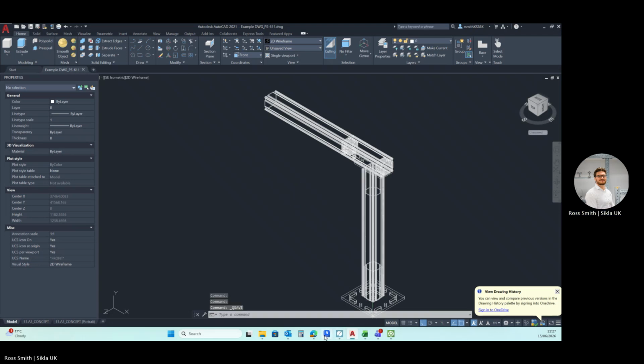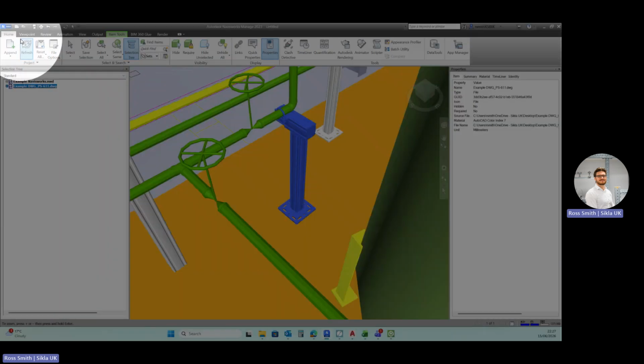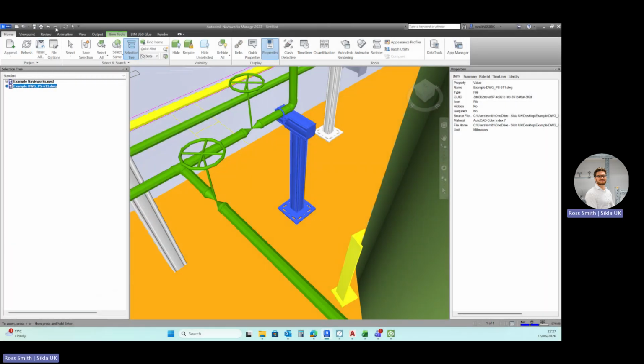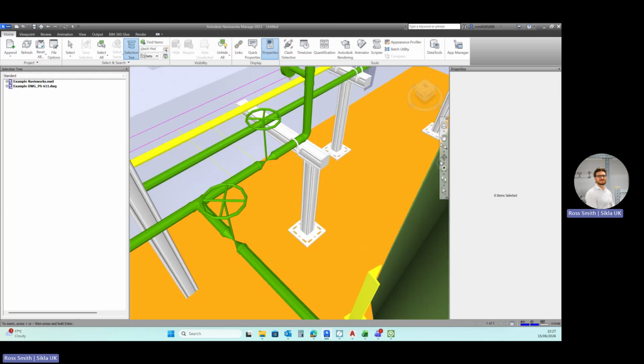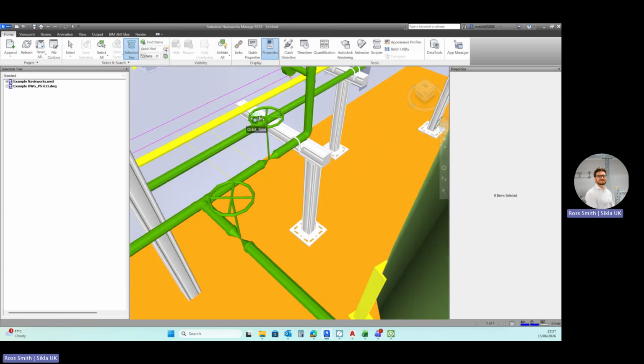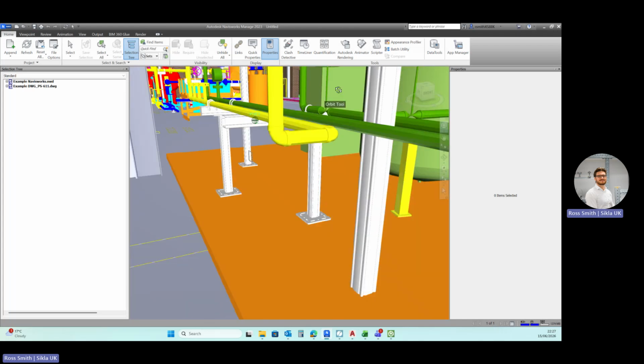Okay, open up my Navisworks. In the home bar, we want to hit refresh. Okay, it's also pinned to the quick access toolbar, but let's hit refresh and we should see the extension of what we've modeled. Okay, it looks like 800 was a good guess to pick up those pipes.